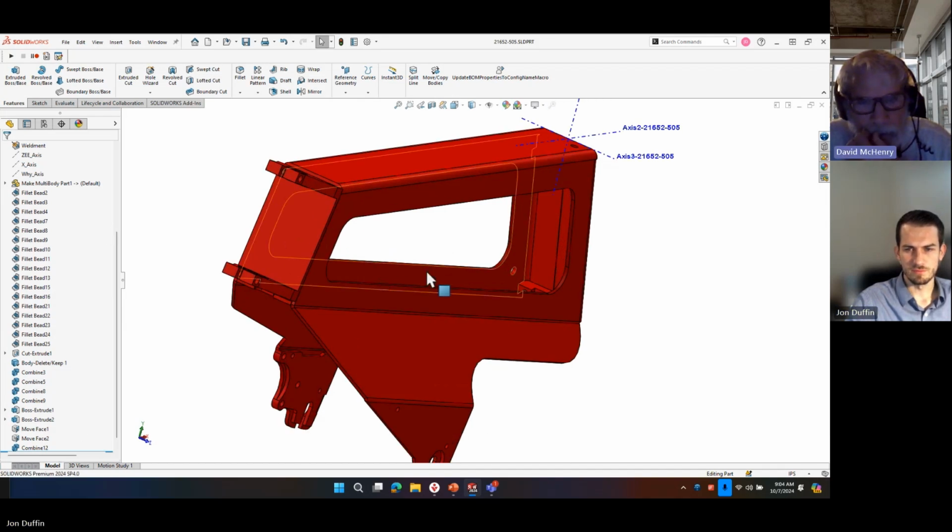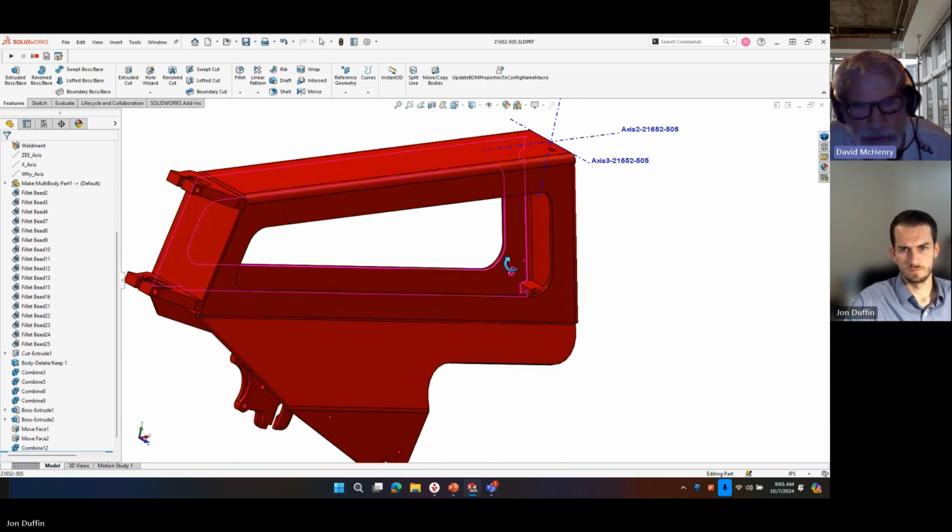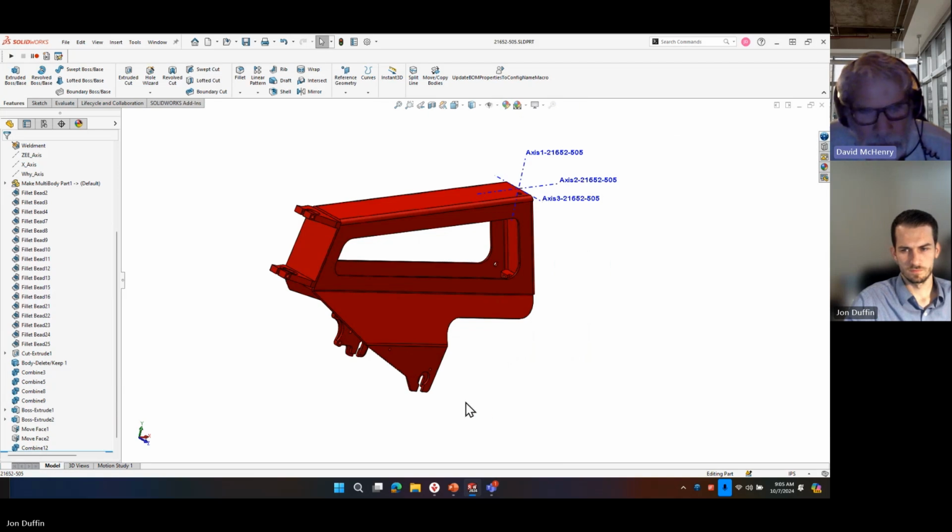Awesome. So the modification that I made, which is cutting out this big window and seeing how much that reduced the weight, this model would be about ready if we define the boundary condition of this being fixed and this being a load. We could potentially fix each of the pin holes as one fixed point, and then load these.